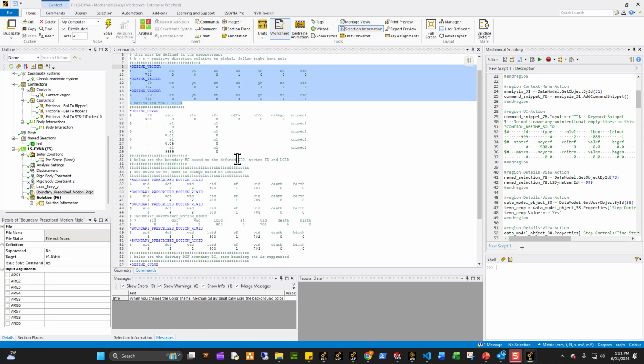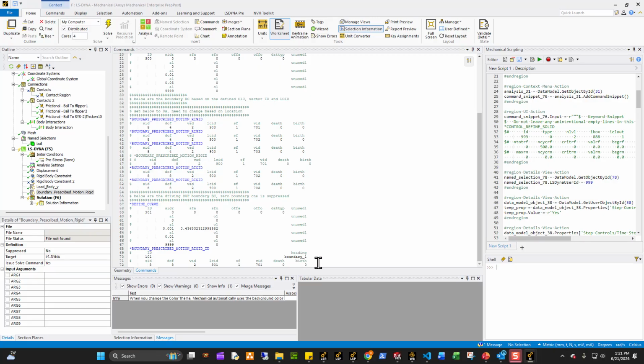And then for the x direction rotation, which is going to be controlled by this card, I'm going to cause it to rotate, and this VAD equal to 2 means it's a displacement. I cause it to rotate by this much radian per second, which I think is like 30 degrees or something like that. It's going to rotate this part from 0 to 0.001 second, rotating the flipper by this much. The rotation axis will be the CG of the rigid body. Okay, so that seems like a lot based on just essentially code, right?